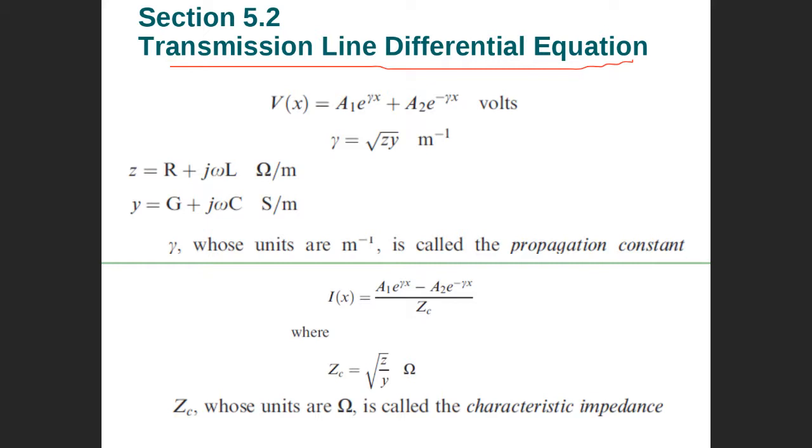You want more accuracy, then you go to medium transmission lines. Even more accuracy, you go with long transmission lines. So you need to find A, B, C, D for a long transmission line.